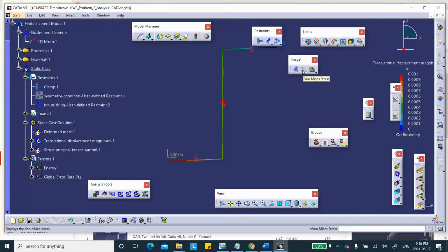For a beam, the question is, at a cross-section location, where do you want to take your point where the components of stress are calculated? Some packages allow you to tell the software at what location on the cross section you want to plot the von Mises stress, and then you get some information. In CATIA, it won't let you do that because its beam capability is very limited.